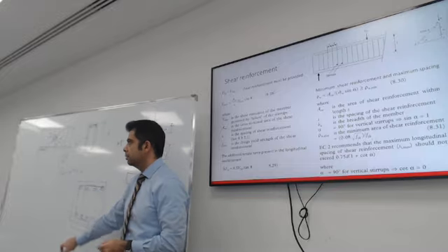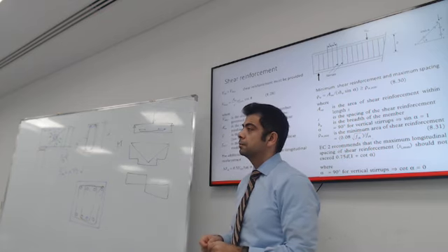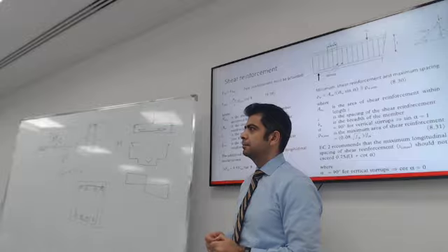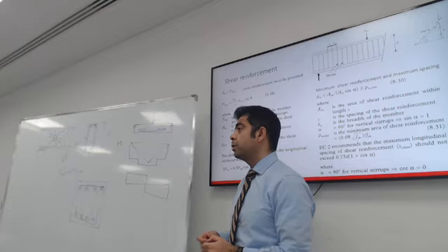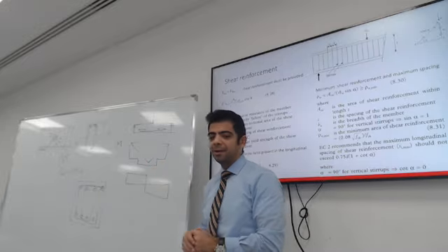I understand the area of the stirrup, but there was an example where we used two different areas of the steel. One is the diameter of the circular area of steel, and the other is because we're looking at it from the side, we're not looking at the circle. So we're taking the rectangle. No, you take the area of the cross section, the circle. All right?